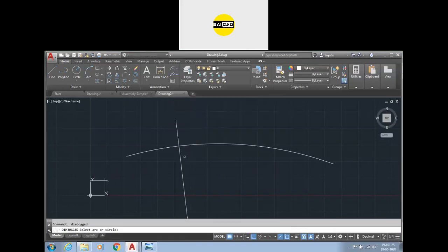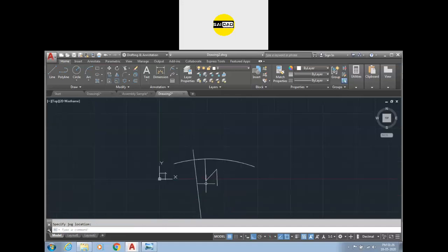So go to the jog, select the arc, select the center location. I want to specify the center here. Now it will ask where you want to specify the dimension location. So I want my dimension to be here, and it will ask you where you want to specify the location of your jog. This shape is called jog. Just click on that point.